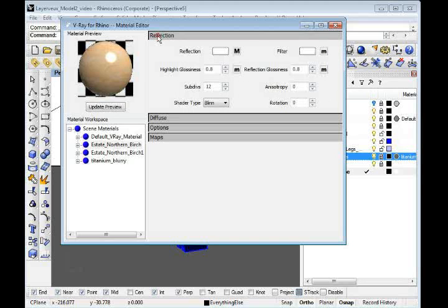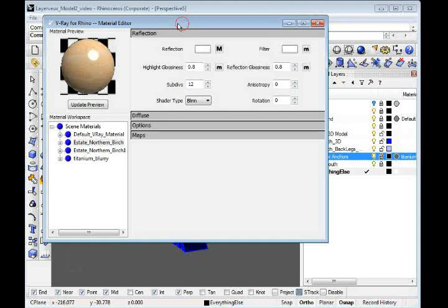Now to intensify the reflection or the glossiness, you can come in here and turn down these values. It's recommended that you don't turn it down below 0.5 on both of them, because in reality, if you turn them down, it gets closer to the realistic material. But if you do that, then you intensify the time of rendering for this particular model, and you could have a very complex project and increase the render time by nearly, we'll say 1.5 times or double. So watch out for that.